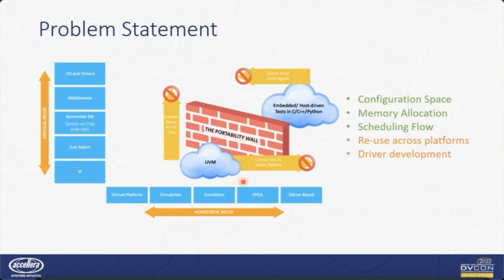So the development of PSS was expected to break down this wall and merge these two diverse worlds. But if you see the current PSS world without HSI, the PSS solver will handle your configuration space, it will handle memory allocation, it will do your scheduling very well, but it actually doesn't help you much with reuse across platforms, and it doesn't really help you with driver development. So the PSS users would usually work around this limitation by using certain tricks, which would mainly involve having a separate set of exec bodies for each target platform.